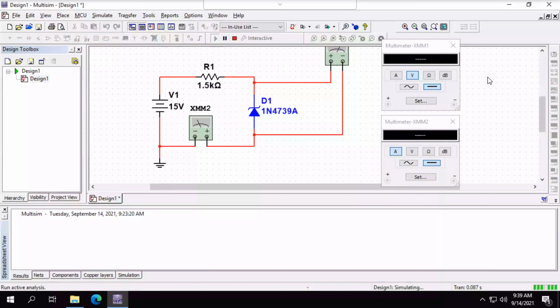So going back to positive, it should drop about 9.1 volts. So that 9.1 volts is at a certain level of current. So we're a little bit below that level of current most likely, and that's why our voltage is coming out a little bit lower. Just like when we have a conventional diode that's supposed to drop 0.7 volts and it ends up dropping 0.6 or 0.65. It's the same idea. Okay, so you can do that with the forward bias and reverse bias to get those measurements.